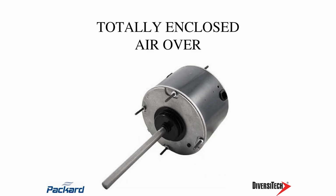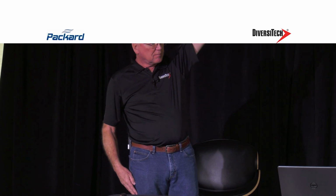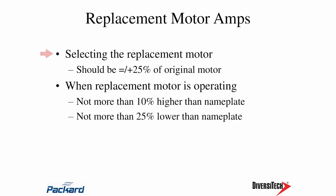And so we use a rule of thumb when we replace these. And the rule of thumb is that if this is the bad motor, my replacement motor should be equal to the amps of that motor, the nameplate amps, the FLA to that motor, but not more than 25% stronger.